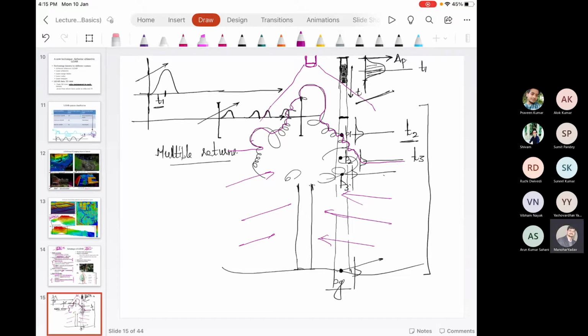While in the case of LiDAR, you are calculating the coordinates of this point, which is hidden within the outer exterior of the tree. You are even getting a point coordinate here, and the pulse finally reaches the ground, so you are getting information about the ground terrain as well. In dense forest, you can't get pixels from the ground. Why is it so?